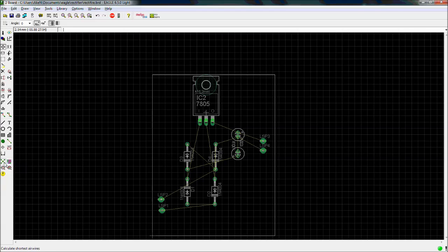Now we have one tool called rat nest. You can see in the dialog box, see over there, calculate the shortest air wire. This rat nest button will automatically calculate the shortest distance between any two terminals. Now look at the circuit, I am hitting the rat nest button. You can see this, the wires get simplified. Fine.